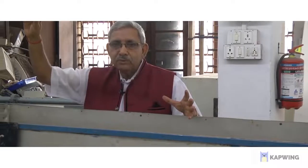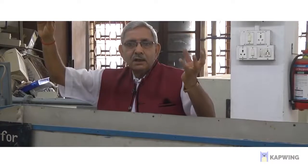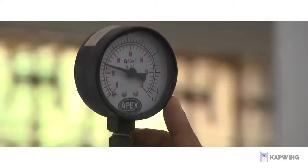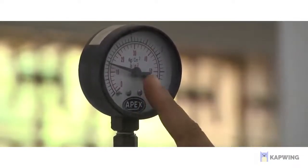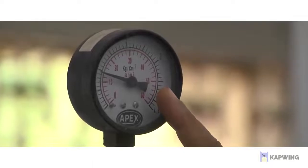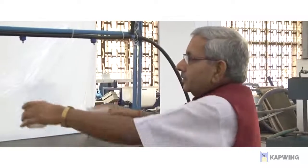We are now going to start the test and collect the data from these drippers. The operating pressure to supply water in the drip lateral is 1 kg per square centimeter, which is equivalent to 10 meter of water column. We start.